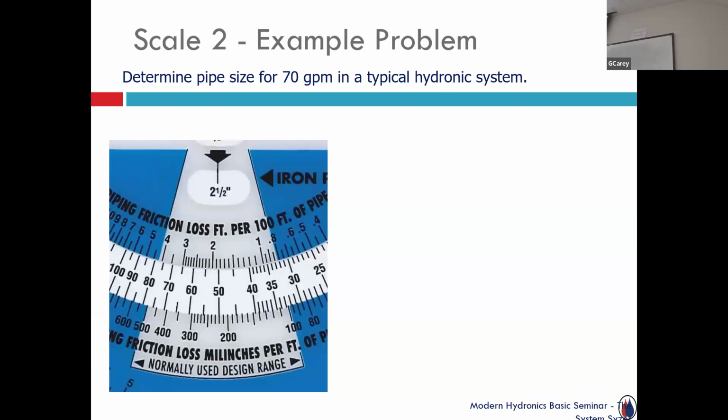But anyway, so then it says, hey, what size pipe to support that 70? After I've established, hey, I got a 700,000 BTU boiler down in the basement, I got to pipe it. It's got to go somewhere. What size pipe am I using?